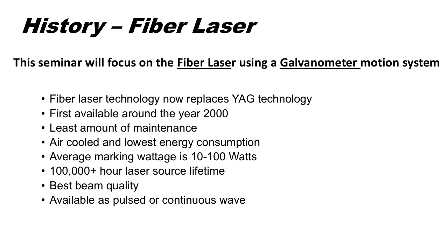Average marking wattage is between 10 and 100 watts. Systems typically can run over 100,000 plus hours of source lifetime. They have the best beam quality, and they're available as pulsed or continuous wave lasers.